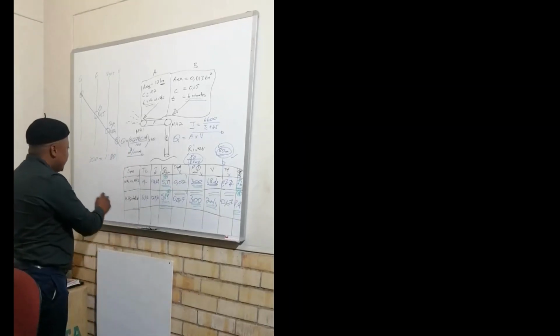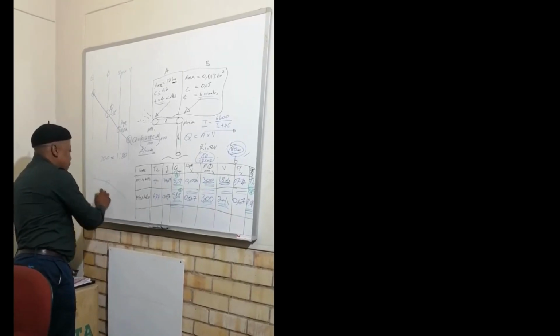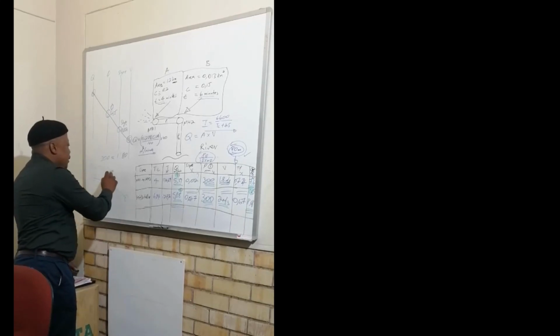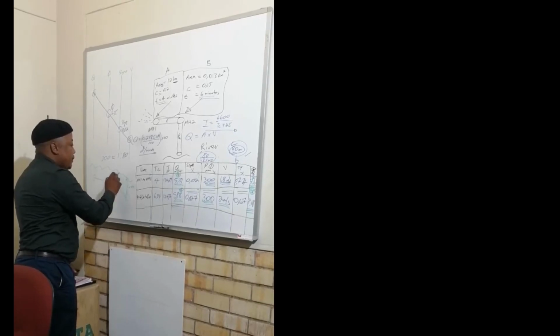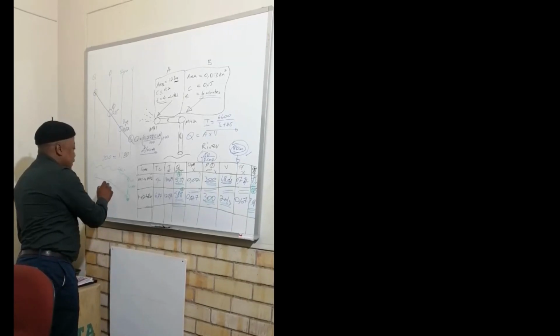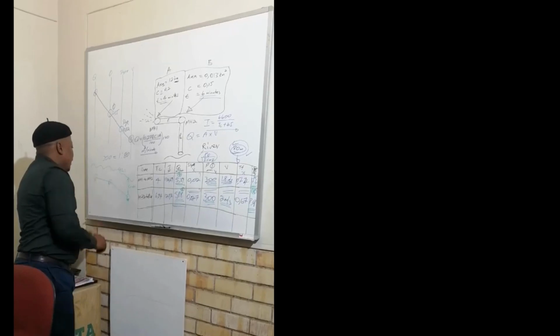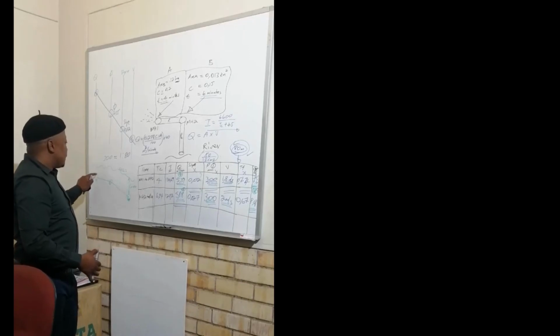Now again, in addition to that, if you look in terms of the slope and the pipeline, that is what you'll be getting. Now, assuming that there is a possibility of cover to pipe, that will be your cover to pipe, and those will be your ground levels, you see. Now, in the next questions, they might want you to determine the invert levels at these points. In determining the invert levels at those points, you simply take the ground level, subtract the cover, subtract the diameter, and you know the level there.